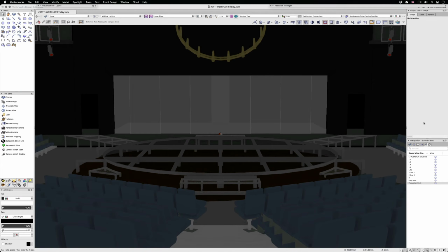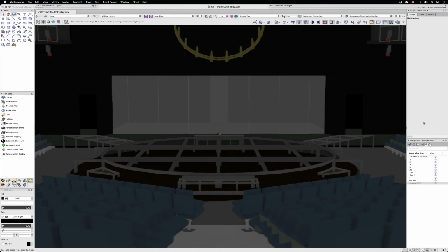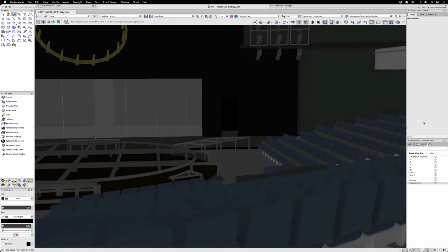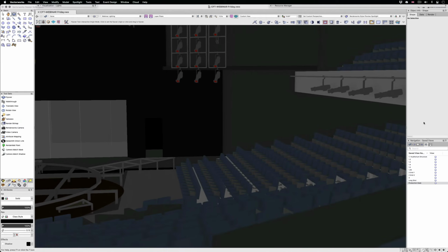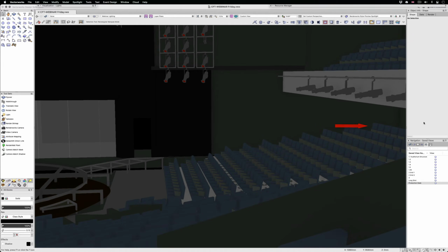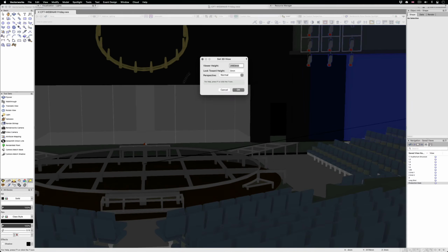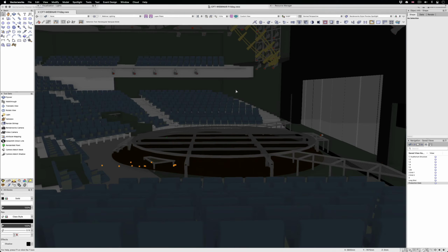However, this is the best seat in the house, and in a theatre such as this, where every seat should be considered more or less the same, I'm going to need to take a look at a more extreme example. I'm still concerned about the first test that I did, so I'm going to check this extreme side seat here to make sure. As I run the Set 3D tool again, the master snaps appear as I hover my cursor close to them. I pick the correct one, and then complete the command.